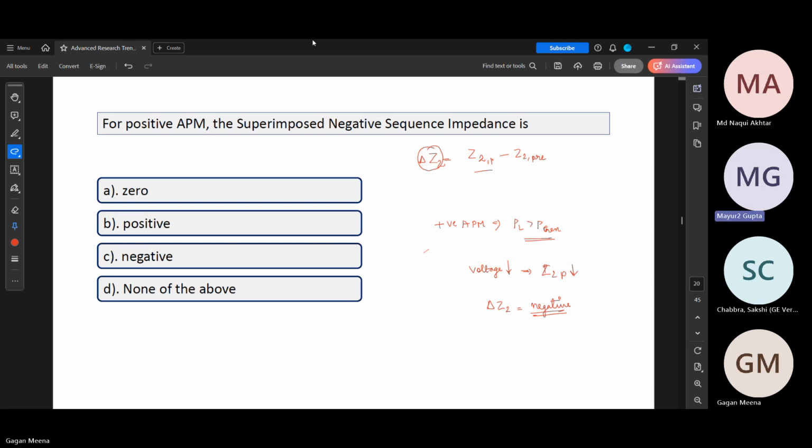And Q, if the voltage starts dropping or the voltage is too high, then they are supposed to absorb reactive power. But what ma'am is saying, or what we are saying here, is that when we are talking about a distribution system, and especially a microgrid, that microgrid is a very small part of the main grid. Any loss of load at the microgrid will not have a very significant impact; the impact on frequency will be in the second or third decimal point.